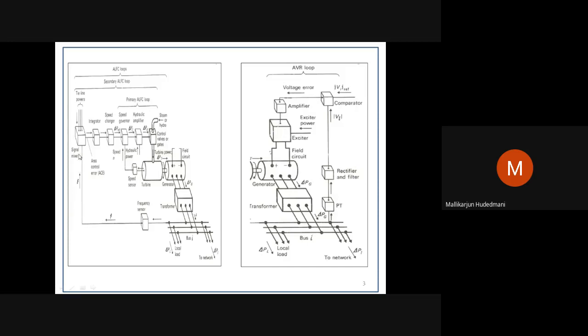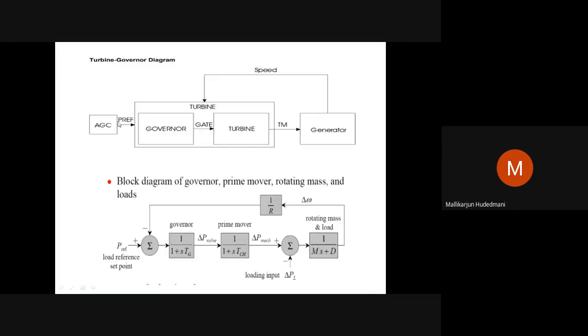So it is very necessary to take a line frequency feedback as well as the power it is transacting, and transform that into error. If the system does not have any frequency deviation, the governor definitely does not need any change of P reference here. If the governor is meeting the requirement, there is no requirement of change here. If the governor does not fulfill the requirement, and deviation is still noticed, then the governor stalls. It cannot perform better than what it is right now doing. Then revision of P reference is very necessary.